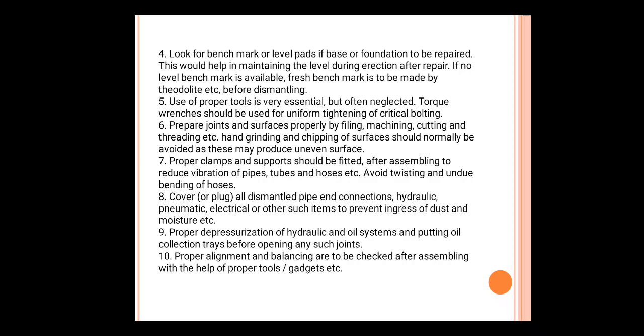Ninth, proper depressurization of hydraulic and oil systems, and putting oil collection trays before opening such joints. Proper alignment and balancing are to be checked after assembling with the help of proper tools and gadgets.